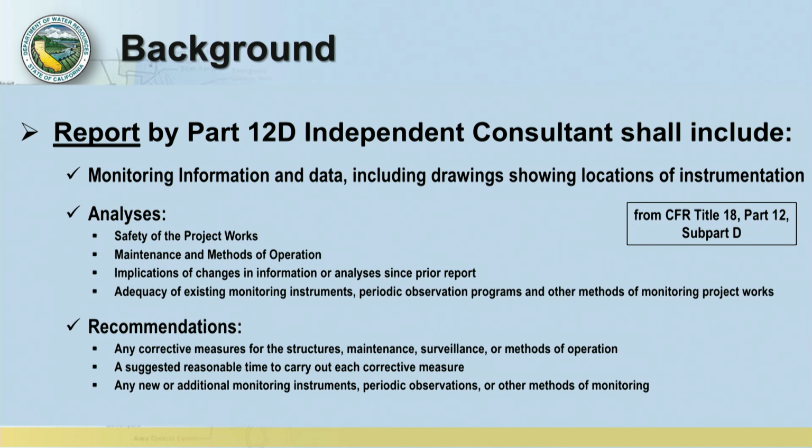The independent consultant shall issue a report, and the report has to have these things. It has to have monitoring information and data, including drawings showing the locations of the instrumentation. Analyses by the independent consultant, analyses of safety of the project works, maintenance and methods of operation, implications of changes in information or analyses since the prior report, adequacy of existing monitoring instruments, periodic observation programs, and other methods of